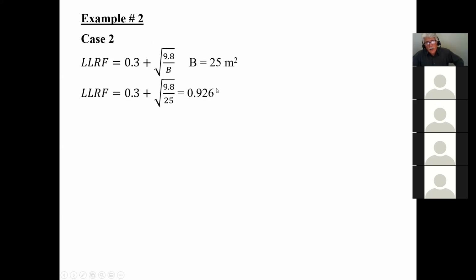So I can take my live load and multiply it by this factor and reduce it by about 8%. So now the formula becomes 1.25D. That doesn't change for load combination 2. But here, instead of just multiplying by 1.5, I will also multiply by my live load reduction factor, but only on the live load, never the dead load.